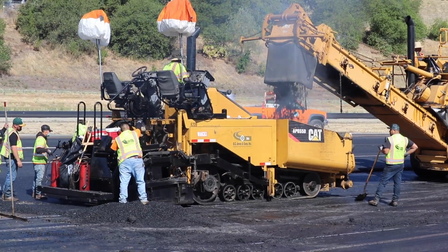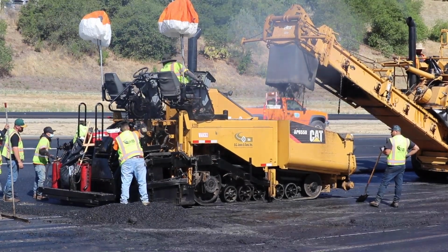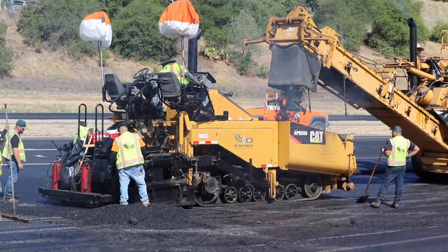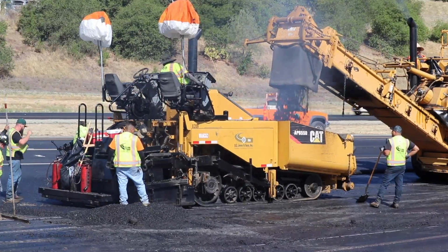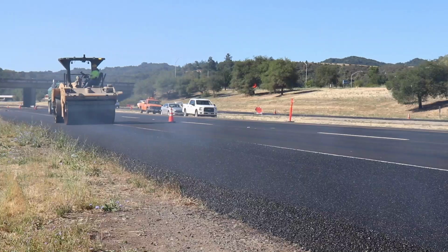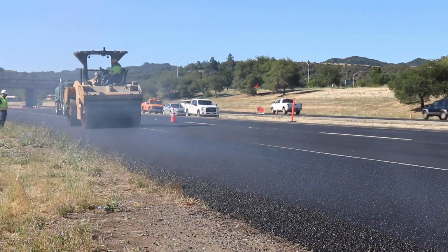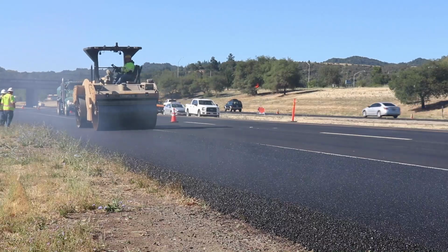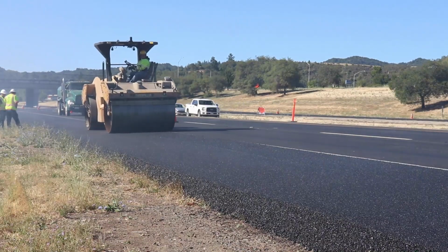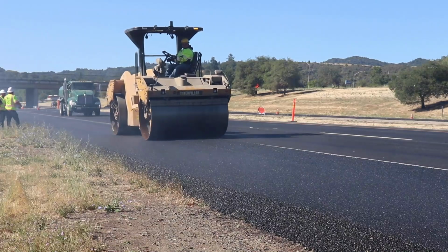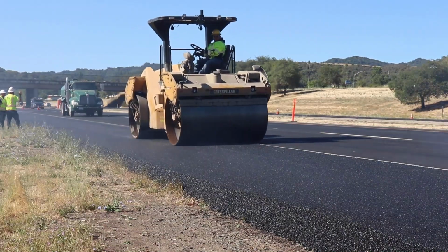Good practices for conventional HMA placement shall be adopted. Special attention should be paid to temperature management. Coordination of the binder production, mix delivery, placement of material, and compaction are essential to provide for the service design life of the pavement. In short, density is controlled by the material temperature and compacted effort. 95% of the compaction density can be achieved during the breakdown rolling process.